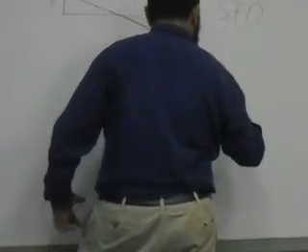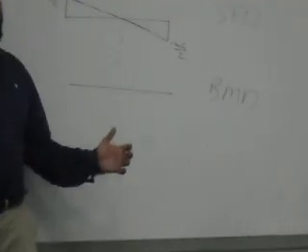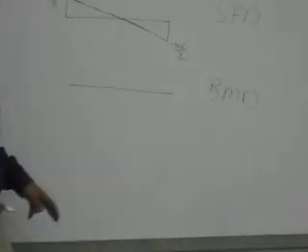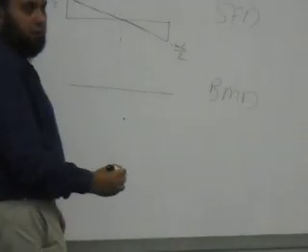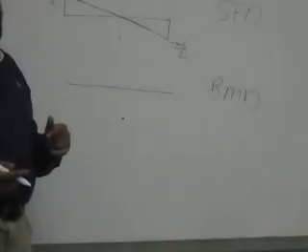Right. Our bending moment diagram, since the zero shear is exactly at the middle, where am I expecting my maximum value? Exactly at the middle, at the zero shear. So the maximum value of the bending moment will be here, in the middle. Okay, right. What about at the edges, at the supports? It's zero.